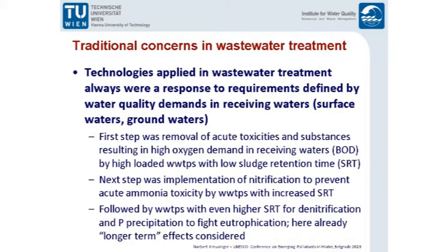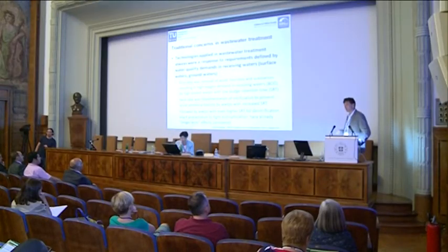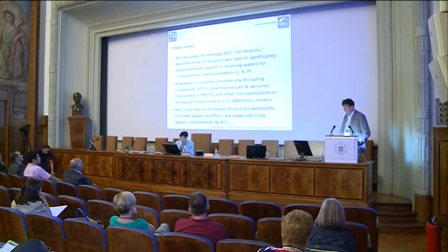And then after the nitrification step, we had an additional one, and here we are already heading towards long-term effects, not the acute toxicity test effects, but eutrophication, removing the pressures for eutrophication, nitrate (NO3) or the phosphorus by precipitation, again here with an even higher sludge retention time. So this was the history of wastewater treatment. And right now we are facing a new challenge, a new approach that again requires the adaptation of the technologies we have available for the new challenges.